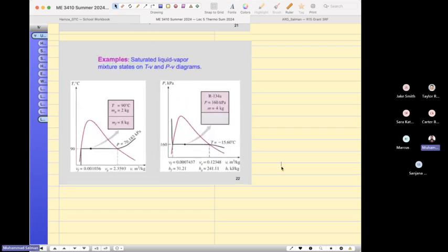Now this is a pure substance, not water, but R134a. This is a gas which we use in our air conditioning HVAC system, and the properties are given as such. At this temperature, what is the saturation liquid vapor mixture? So for R134a, you see, all this is sub f, and this is all sub g. So if I say, what is the property over here? You will say, Professor, this is the formula for any property inside the latent heat region.